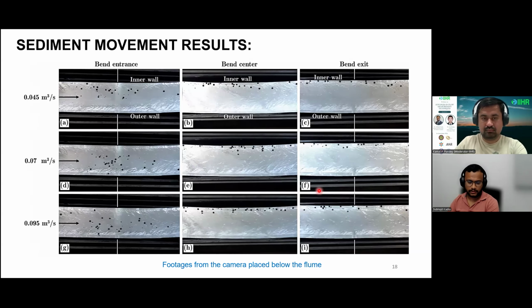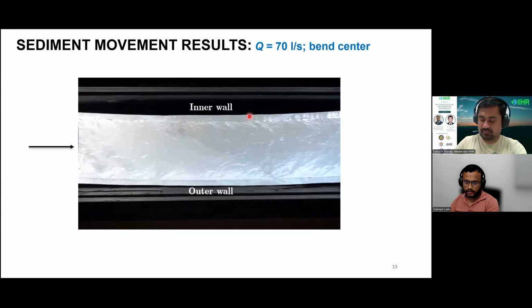And now the comparison of the sediment transport. You can see in the upstream part of the bed, or in the straight part, the sediments are basically spread across the whole channel. However, as the secondary currents of type 1 develop in the curved channel, further downstream we see the sediments are pushed toward the inner wall. Although we have to remember the bed shear stress is higher toward the outer wall, and that was a very interesting phenomenon that was observed. And finally we have the reason why we have deeper abrasion toward the inner wall. Another video, unfortunately, did not work.